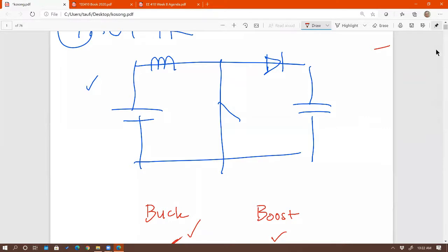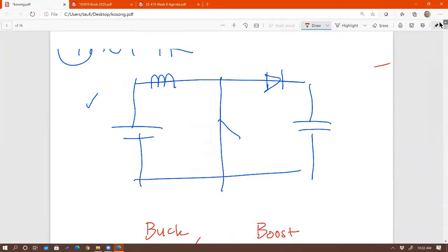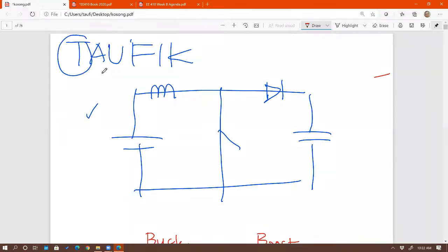So start with T, the T network. Of course, I'm only joking when I said my name, but if that is useful, go ahead and use it. But I always start with the T network, and then start placing the components that way. For a buck, input is a switch, output is inductor, middle is the diode. Boost is the opposite, so inductor moves to the front, and it's just rotate counterclockwise with respect to a buck. Then you get inductor, switch, diode for a boost.